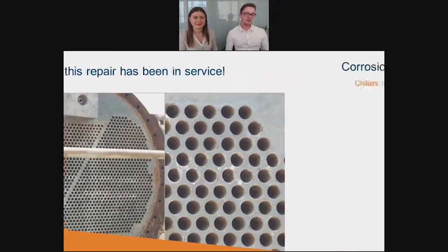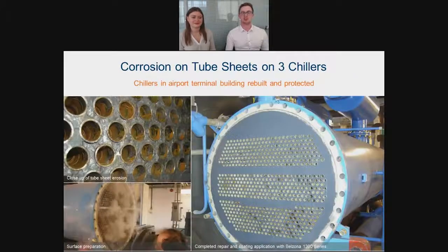Yeah, so a similar sort of vein to the previous one that Marina was just talking about, but this was more of a commercial type application because it was in an airport in Stockholm in Sweden. In some cases, the cooling water that's used within the heat exchangers isn't necessarily brought from a pure water source. The water supplied to this heat exchanger came from a local river system, which meant it came with lots of other undesirables within the system. Mainly, the thing they didn't filter out was the salt. And obviously, as we know from marine environments, corrosion accelerates massively when there's salt involved.